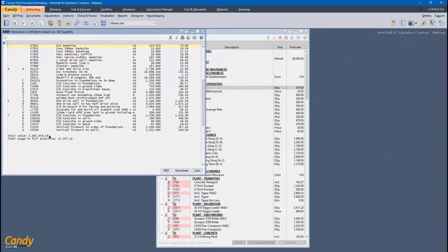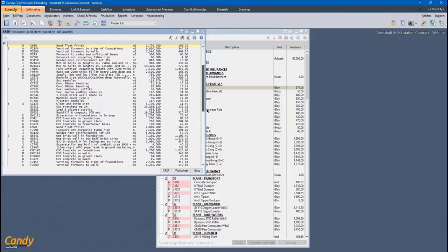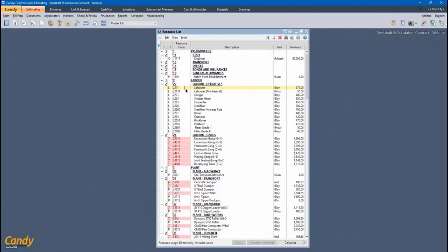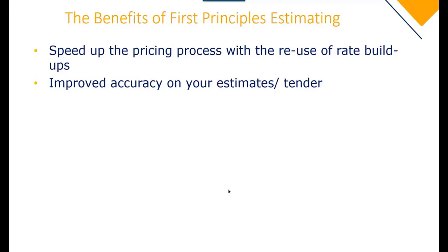And you'll see there's that 5.6 million for that laborer, and the utilization 15,207 days. And that's built up of these individual items. So to clear the site, 21 days of labor has been allowed. Bulk excavation, 467 days. And all of this contributes to labor. If I change the rate here in my bill, it's going to change the rate throughout the bill of quantities.